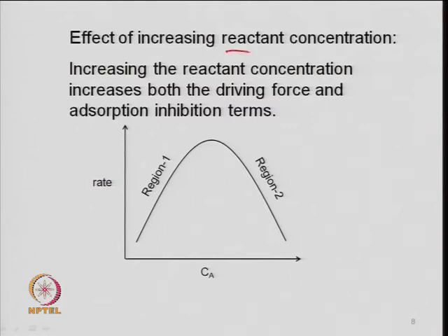So, effect of increasing reactant concentration, that is cumene in this case, right, and sometimes you can see the effect of product also. When you study this experimentally, you can add some product concentration in the feed itself, say propylene, the effect of partial pressure of propylene, or in this case the effect of partial pressure of benzene. Along with the feed you add some propylene or benzene and check the effect again, because the benzene will adsorb on the surface if it affects the rate. If partial pressure does not affect the rate, it means whatever the different concentration of benzene in the feed, the overall rate will not change.